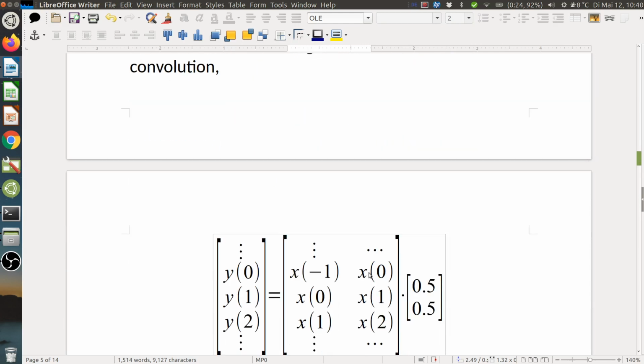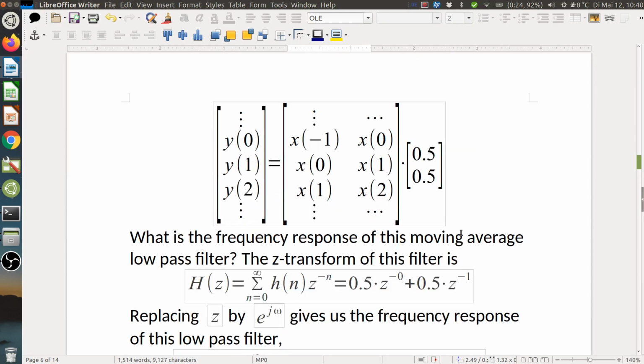Yeah, we can also use this matrix formulation, which is a little bit more practical because it has, in this case, the finite impulse response as a finite vector here from the right-hand side. So now here the coefficients appear as a vector on the right-hand side. And then the matrix contains the signals as far as it concerns the filter.